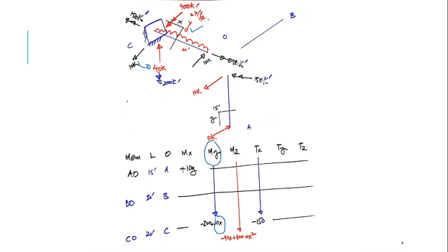Also, we have this pure moment 200 kip-foot. This is in Y direction and this is applied at support, so this would be resisted here at this point with equal and opposite 200 kip-foot. You should know that this is clockwise and this is anti-clockwise, so I have mentioned minus 200.